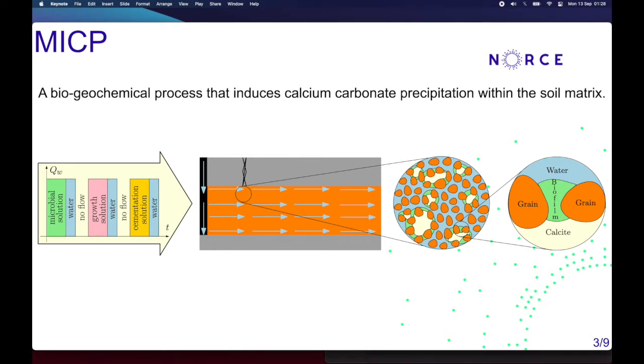That is, in the space domain, there are one liquid phase, water, and three solid phases: the biofilm, calcite, and the rock matrix. The microbial medium, growth components, and cementation solution are dissolved in water prior to injection, and they are transported only in the water phase by advection and dispersion. The biofilm and calcite are assumed to be impermeable and incompressible. The governing processes in the biofilm are growth, death, attachment, and detachment.